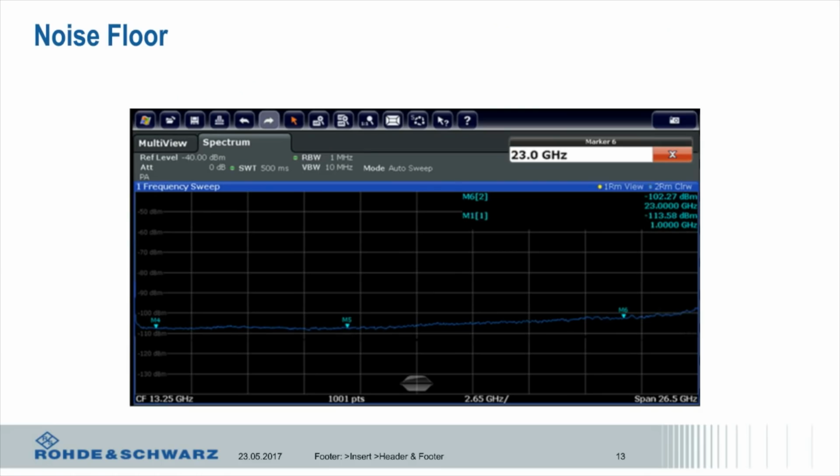Okay, so this is just showing you a plot from a spectrum analyzer, and I work for Rohde & Schwarz again, so we make these, so I have to put some slides in here showing our products. But you'll see here it's showing you some markers in a noise environment. This is just noise from the overall environment, and it's at a frequency where there aren't spikes. This is just thermal noise, i.e. noise from the sun and everything around you.